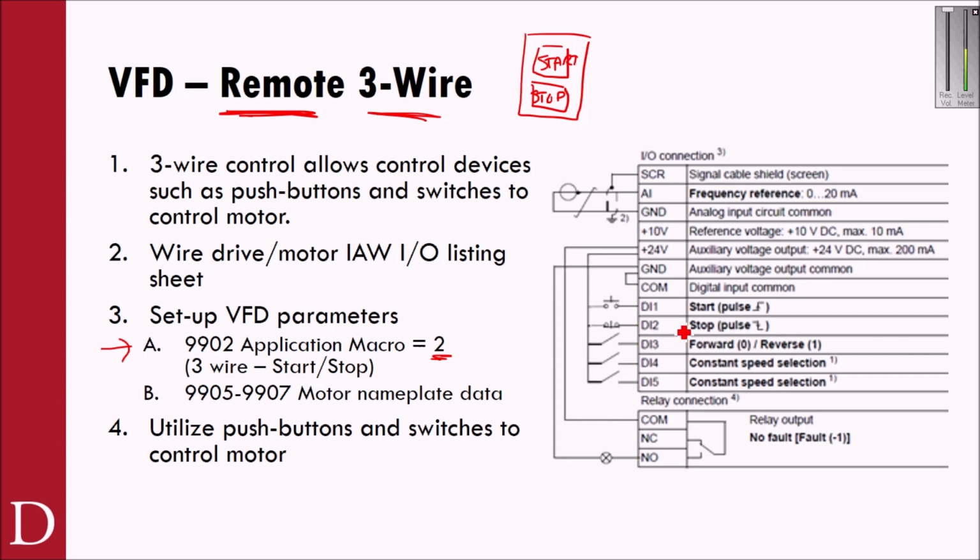in 3-wire. So what that means is, and when we talk 2-wire, 3-wire, this screws people up sometimes. 2-wire we typically think of like a switch. 3-wire we typically think of like a push button. And the reason why we think of it like a push button is because it's momentary, and a lot of times it requires that 3rd wire. This only requires 2 wires. In 3-wire, we require that 3rd wire for a holding contact.